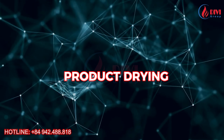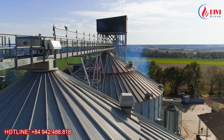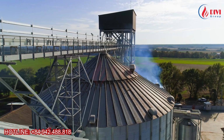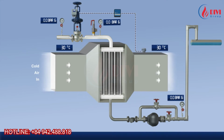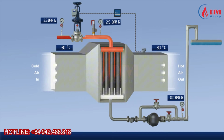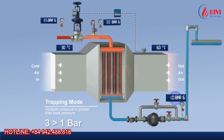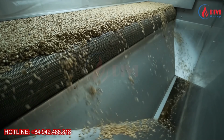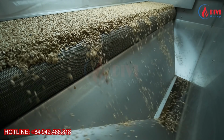Application 2. Product drying. Another very common industrial application of steam is product drying. Steam flows through heat exchanger coils. A blower forces air across these coils. As the air passes through, it absorbs heat and reaches the required temperature, whether that's 80 degrees Celsius, 100 degrees Celsius, 150 degrees Celsius, or higher depending on the system design. The heated air is then blown through the product, causing moisture to evaporate.